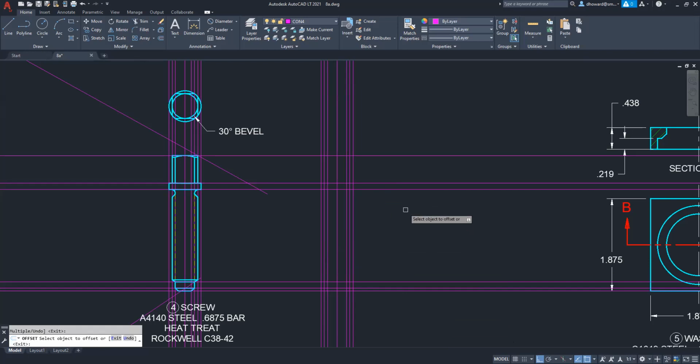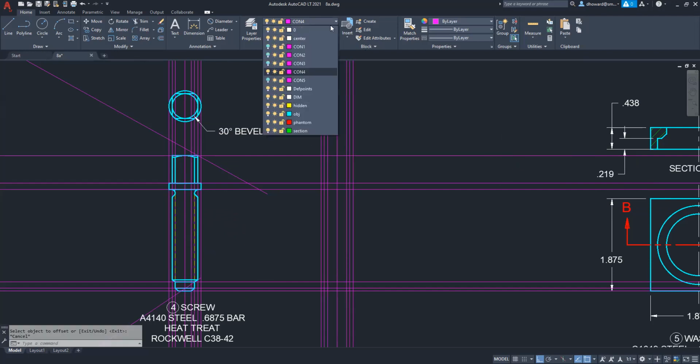Before we draw the front view of this guy, I want to draw the top view. The top view is going to give us some information. It's going to tell us where this line is. And you can see it by coincidence, it happens to line up with this diameter, the one that we just did, the diameter on the bottom, the inside of the threads, and this line right here, this edge, which comes from this intersection right here, just all by coincidence, happen to be the same value. It's really weird. But anyway, let's do that top view now.